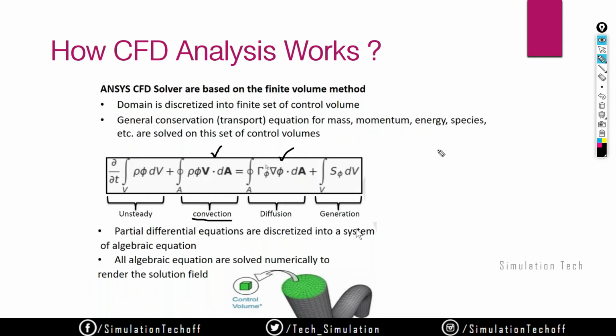But if you are using a laminar flow rather than a turbulent flow, this unsteady term will not be included, and if you don't use any temperature related thing, this factor will not be included. If you don't use diffusion, this part will not be used. So if you suppress these things, the problem complexity will decrease, and the size of the equation will also decrease.